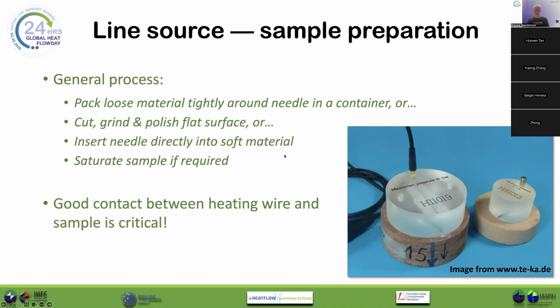With a needle pressed into soft material, that's arguably much easier to do. With a half space sensor probe here, though, you need to apply pressure to keep that heater needle on the sample surface, and may need some sort of contact paste as well, just to ensure good thermal contact.